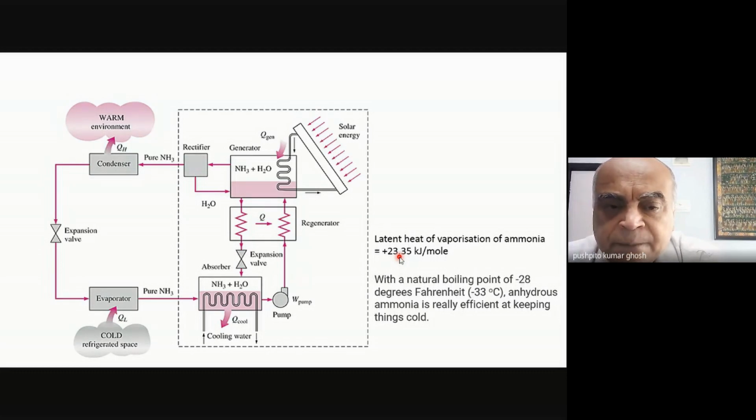So effectively, that's what happens in many of the refrigeration cycles, where I may use a compressor to compress. Suppose it's an ammonia-based refrigeration, and I've compressed it to something like 6 bar, and I've kept the ammonia as liquid, and then I allow it to expand. So it expands and its pressure goes down, and because of that, the ammonia will boil over. And when it boils, it draws its latent heat from the rest of the liquid, and the rest of the liquid becomes cold. So I can bring down the temperature to maybe something like minus 33 degrees centigrade.